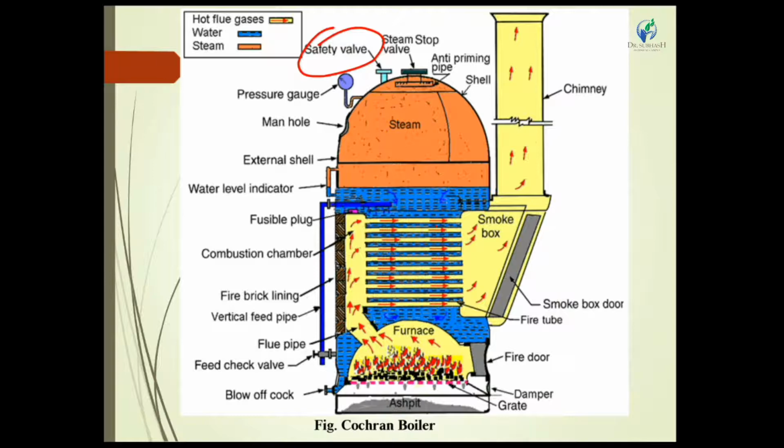As we can show, it is like a normal pressure cooker. If the cooker pressure is high, the dead weight safety valve goes up and lets the excess steam out from the cooker. This is one type of boiler safety valve, provided against higher pressure and critical pressure.